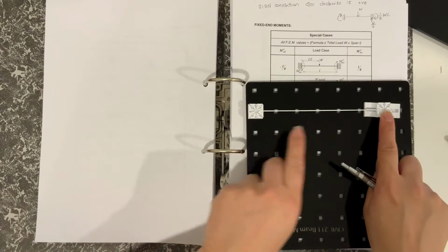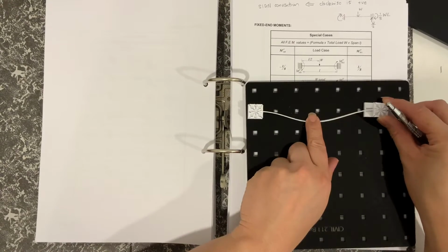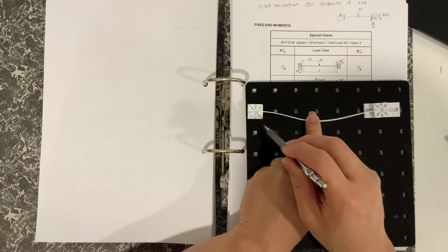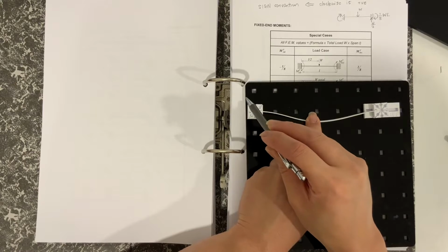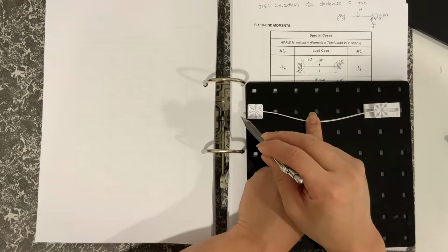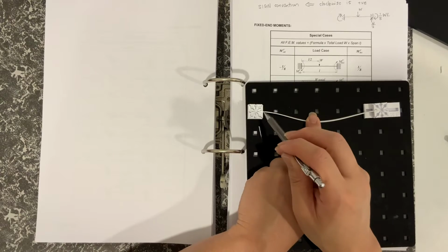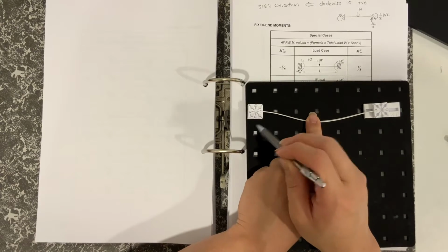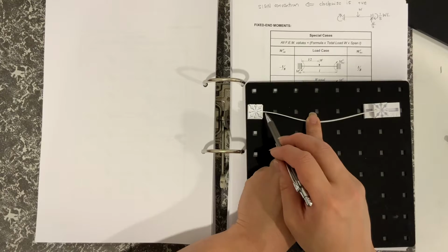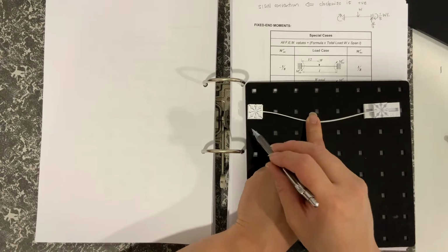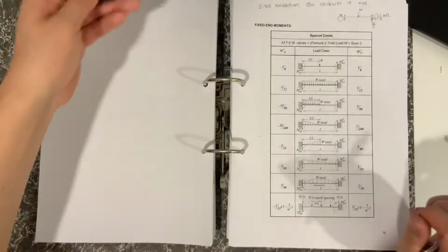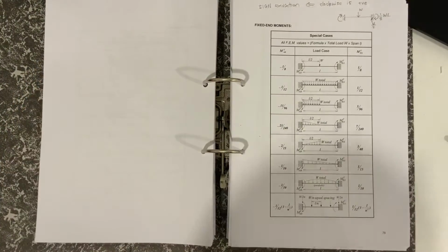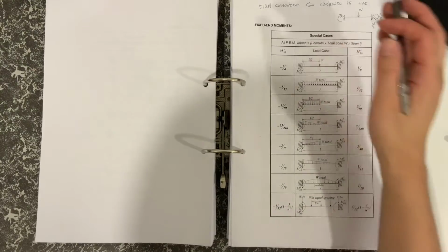Now we know from this case here, where both ends are fixed and you've stuck a load down in the center, that the bending moment or the reaction moment is going to be acting in the anti-clockwise direction. So all the stuff we talked about before tells you that the reaction moment and the bending moment at this point here is going to give rise to an anti-clockwise moment. But now we've got a sign convention that we need to follow, and the sign convention is clockwise is positive.